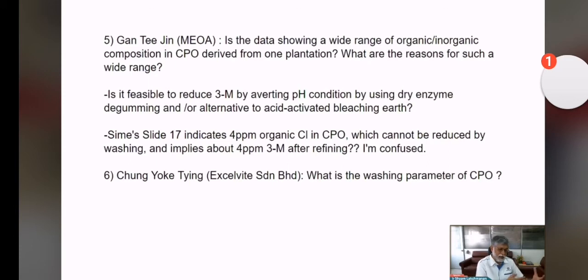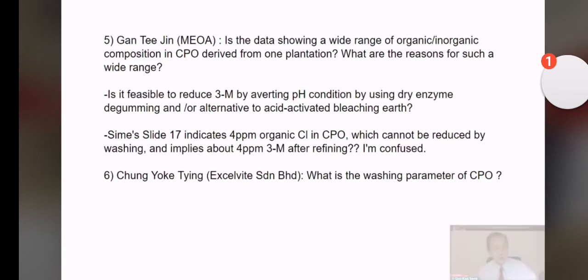There is some acid addition, depending on the process. You may want to do some pre-acid, or it could be post-acid. It depends on each individual operation. But the mixing is important. You have to have an intimate mixing between the water and the oil, because it's two different phases, and that is where the dilution actually takes place during the mixing stage. The centrifuge just separates the two phases from each other. Okay. Mervyn, anything you want to add along those lines? No.